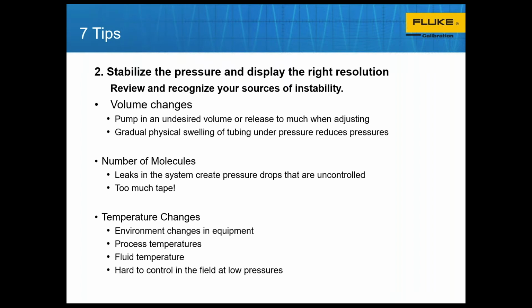So if I pump a certain amount of volume into a system, that is what I'm expecting to generate for pressure, but the tubing itself, as an example, might start to swell a little bit and reduce your pressure, okay? If I have leaks in that system, either the pump itself can't handle it or there's a physical connection leak at a fitting. This shows up typically on pneumatic type connections because they're a little bit harder to diagnose. So you may find that you're leaking out molecules and then your pressure will continuously drop as well.